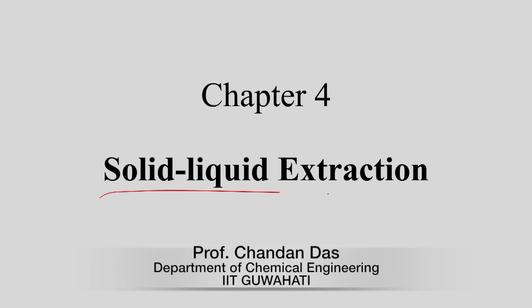Now, we will be discussing solid-liquid extraction, that is the fourth chapter. Whatever we have learned in chapter 3, the liquid extraction, in place of the carrier solvent, it is a solid inert. Inside it the target component is there, and we are adding the extracting solvent from the outside, and then the remaining processes will remain the same.